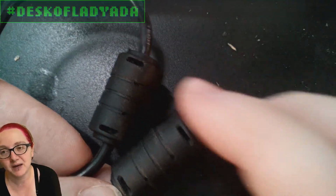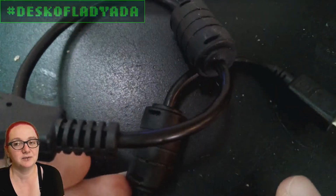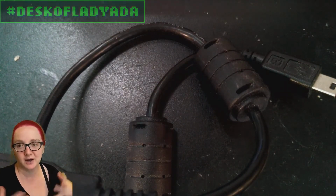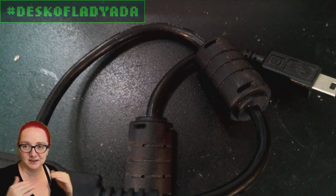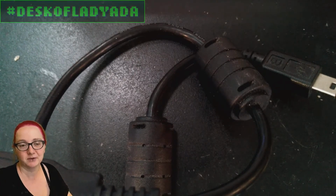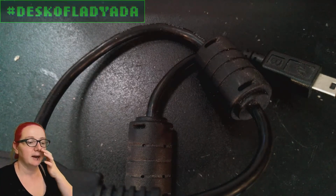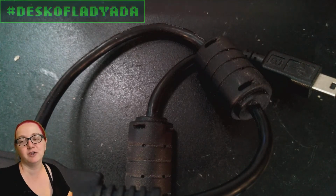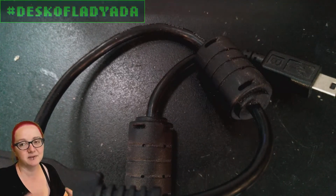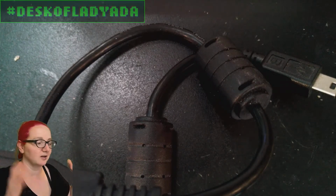But as you saw, there are some cases where you have a device post-installation where you want a clamp-on ferrite bead. And you would use test equipment to determine whether or not it's passing the EMI floor that you're looking for. They're not specified like, this will reduce EMI by this much. They're specified by the width and thickness, inner diameter, outer diameter, material. But there's no magic number like, use this size for this frequency to reduce it this much. It depends a lot on the product you're using, the cable length, the drive strength, the amount of current draw, et cetera.